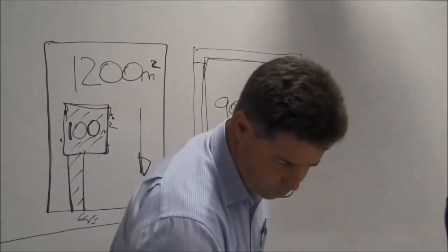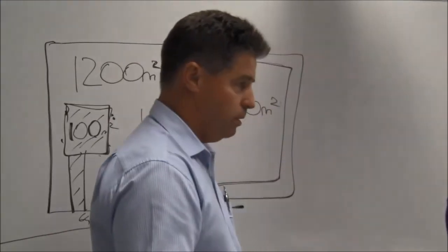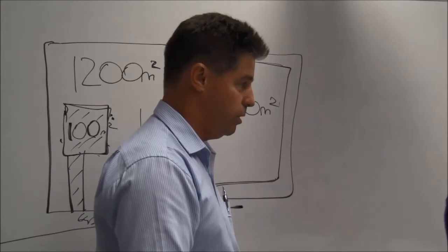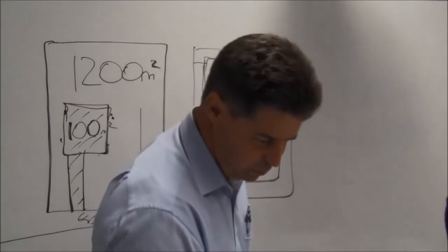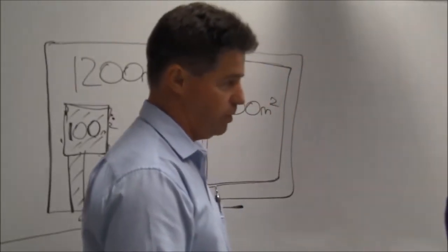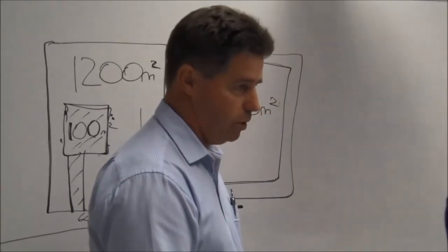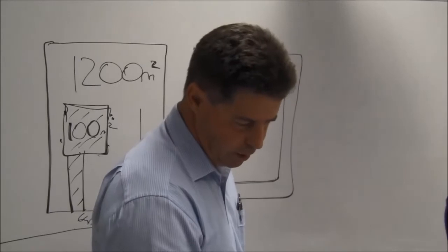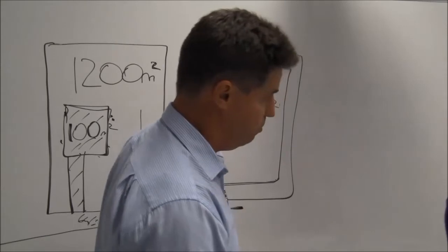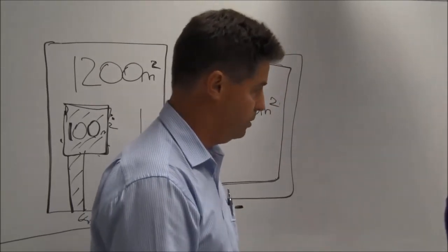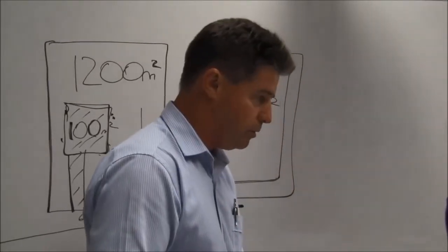So on the table, we have the fraction impervious table. This all comes out of QDM. I don't know if you guys have worked with QDM before, Queensland Drainage Manual. I don't know what happens in other states, so I can't comment on other states. But QDM was a development that was done for southeast Queensland, and it's what councils work by up here. So let's say we have a fraction impervious of 0.85, 85% of the area. Basically we go to that table 2.1, which is straight out of QDM.